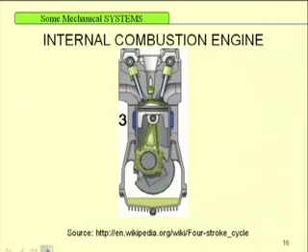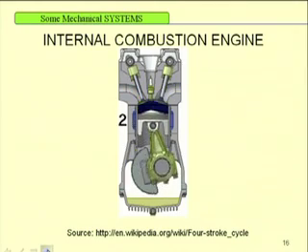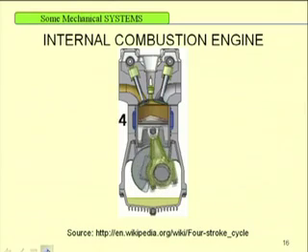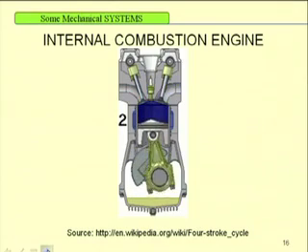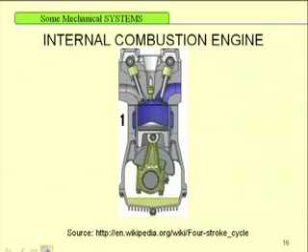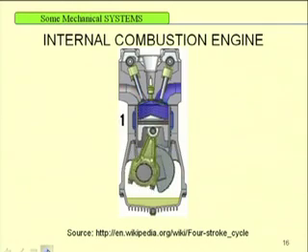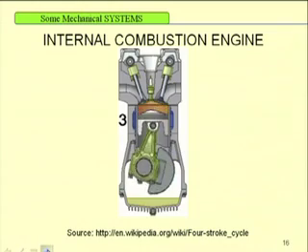This slide shows the internal combustion engine. Here also you can have several parts. This is particularly a slider crank mechanism. In this slider crank mechanism, one can have unbalanced primary, secondary or harmonic forces in the direction of line of stroke.